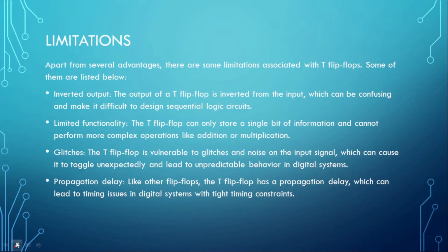What are the limitations? It will provide the inverted output for the given input. That's why it is difficult to design for sequential logic circuits, and it has some limited functionality, so we can't use it widely compared with the other flip-flops. It is vulnerable to glitches and noise of the input signal, and it can lead to unpredictable behavior of digital systems. It has propagation delay like other flip-flops, so there will be a delay to provide an output.